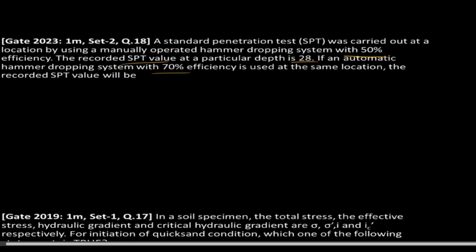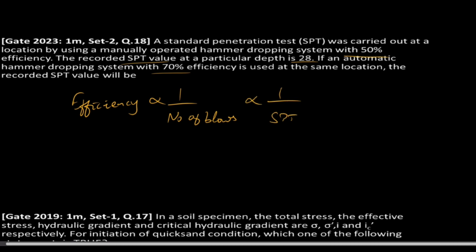So efficiency is inversely proportional to number of blows, which is the SPT value. Therefore, eta 1 S1 equal to eta 2 S2.